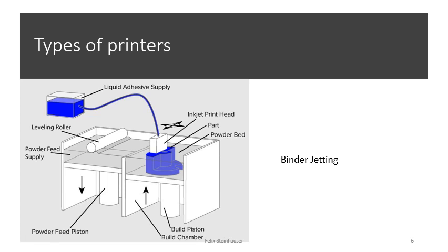Here we use an ink agent, which is like a glue, to stick the metal together, but after it comes from the 3D printer, we have to burn it to really fix the powdered metal together. It's kind of like the sintering process. First you build up your model or press it. Here in this case you 3D print it, and then you have to burn it in an oven so that it gets melted together and keeps its form without breaking apart again.